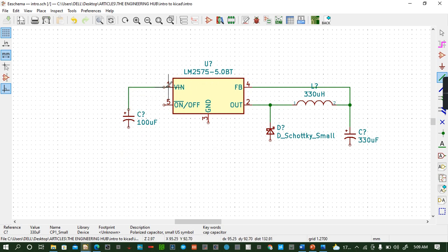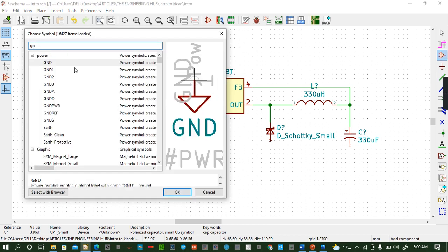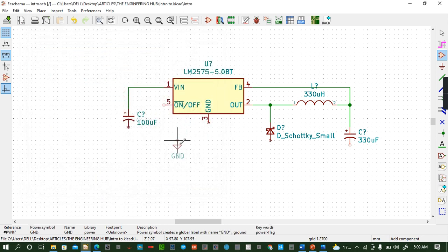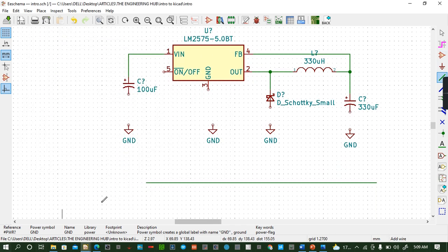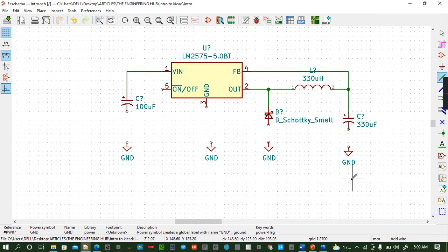Then we have this one at the input. Then we have now to place a component G and D ground. Yes, ground. And in this ground, we are going to ground so many components. So I can copy here, ground there, copy here, ground there, copy here, ground there. So this one, sorry, wire W. Okay, escape. Like that. Sorry, not junction.